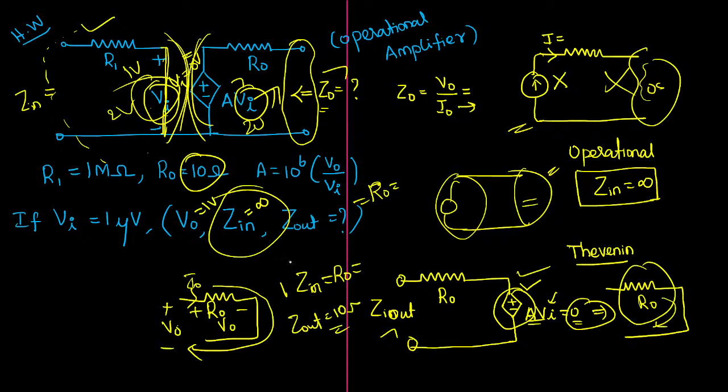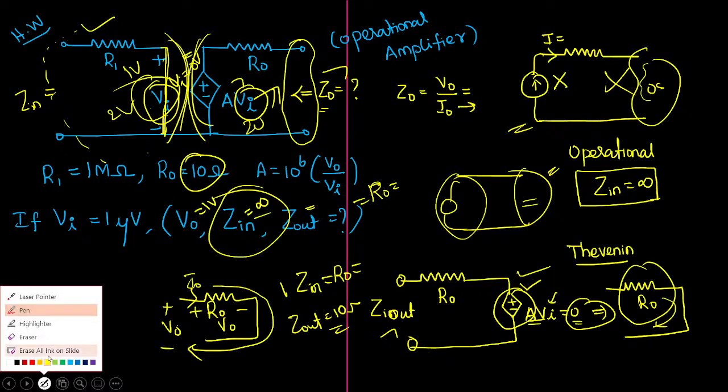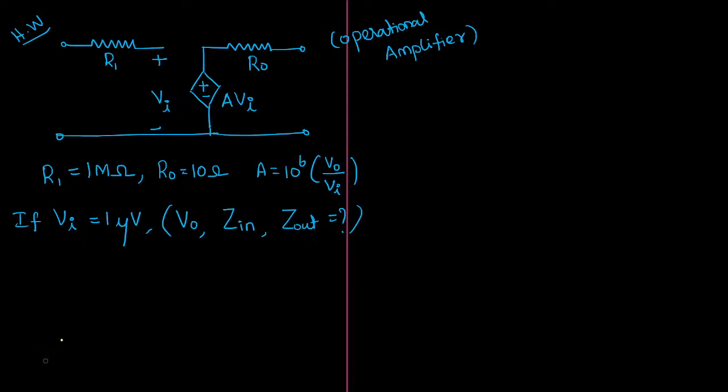Okay, sir. After understanding all these questions, we have calculated output impedance, input impedance, V0. Why have I spent this many minutes here? It's a very simple question. I know that, but we have captured something. Gain of the operational amplifier is 10 power 6. This value is almost practically a fixed value. Do remember this value, first conclusion.